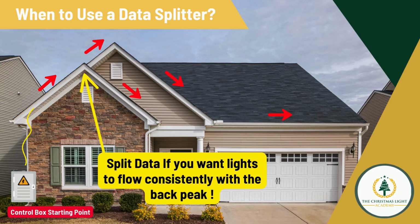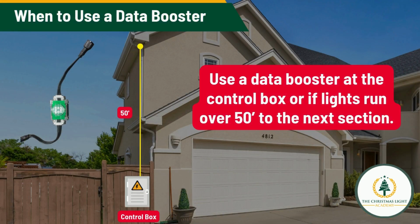Another thing to watch for is long gaps in wiring. If the jumper section you are running is more than 50 feet to the next lighting section, you may need to install a data booster in that jump to ensure a strong and consistent data signal. Since the controller communicates with each light individually, long breaks in the wiring can weaken the signal, causing issues with lighting effects or synchronization. A data booster refreshes the signal, making sure everything works properly.